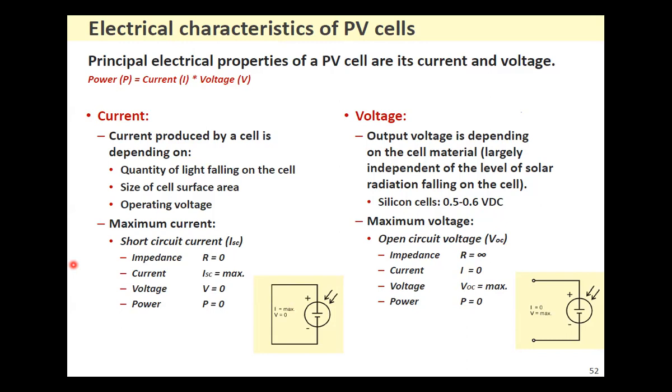I'm trying to say that if you have a PV module, bring it inside your room and test the open circuit voltage. You may get 12 or 13 volts, but as soon as you connect the load, the voltage will drop to 0 volt, because there is no sunlight but only the roof light, and it has no energy.